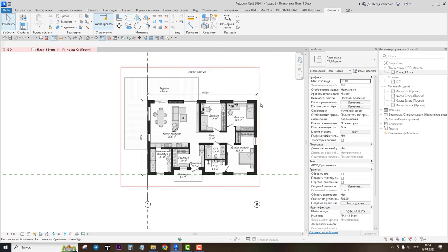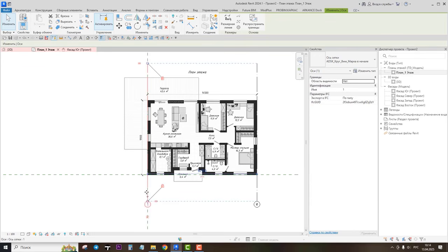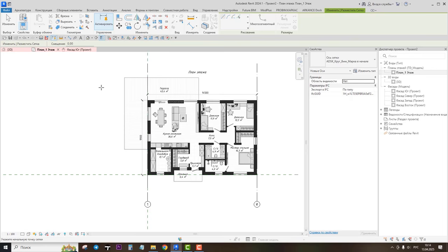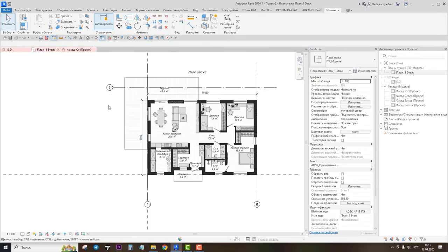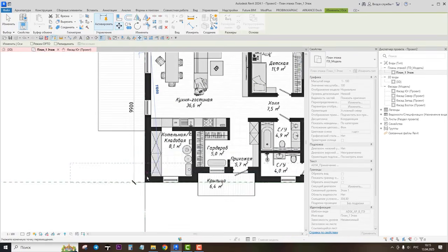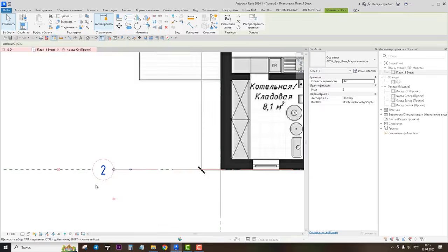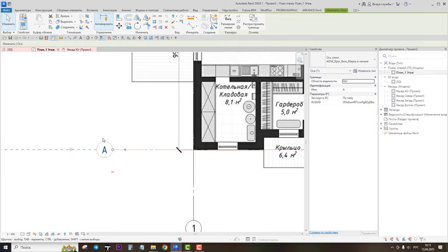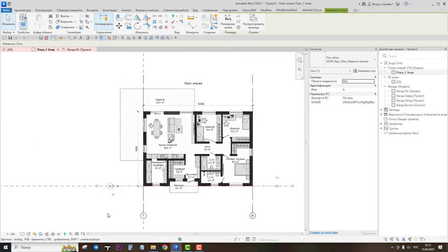Let's make horizontal grid lines. You can choose the line you already have. Select the tool, create a similar one. In a free field, from left to right, make the line. Double click escape. Then select the line, the tool move, and move it to the origin. Let's change the name. Let's call it the line A.